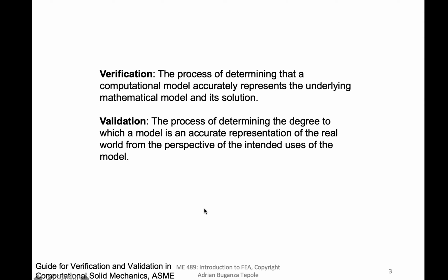Anyways, the things that we introduced at some point in the verification and validation lecture: what is verification? It is the process of determining that a computational model accurately represents the underlying mathematical model and the solution. In other words, are you actually solving the PDE that you say you're solving? And then what is validation? That is the process of determining the degree to which the model is an accurate representation of the real world. In other words, whether your PDE actually represents reality.